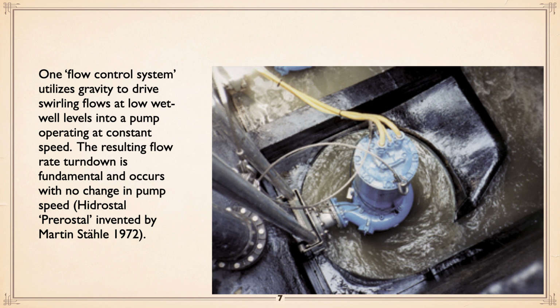Now remember, clockwise rotation of the pump and clockwise rotation of the flow mean that the pump can't perform as well. So what the intent is, when the level's up high and all this stuff at the bottom is flooded, then the pump pumps like you would expect it to, as per the curve. But as it gets into this situation where you've got this swirling action, the pump will underperform and therefore pump at a lower rate. Therefore, you don't often have to actually turn the pump off because its performance will match whatever the inflow rate is. Kind of a cute little trick, like variable speed without.